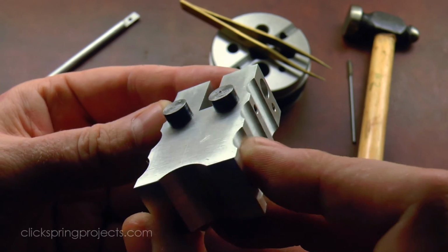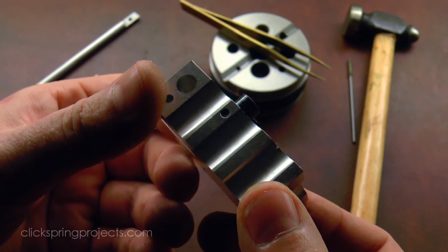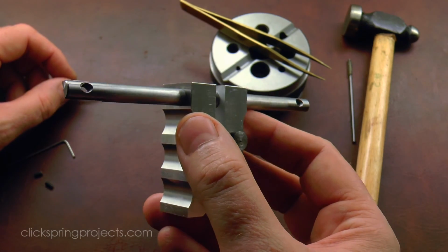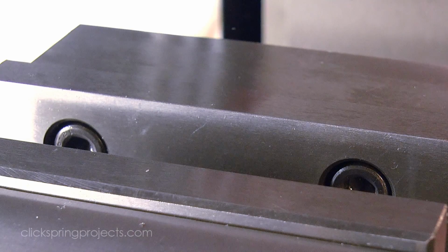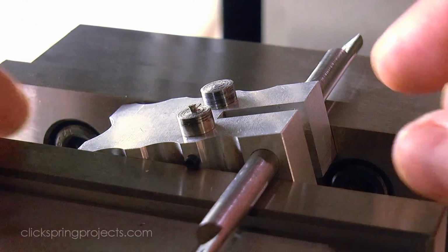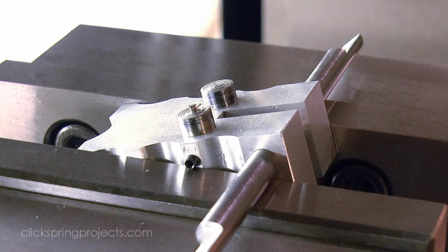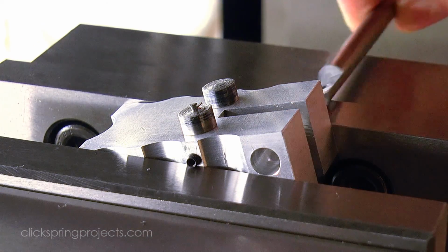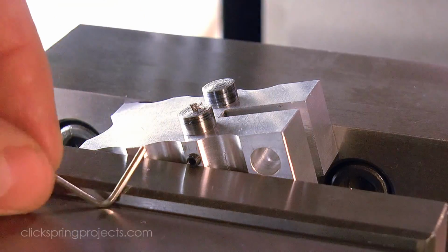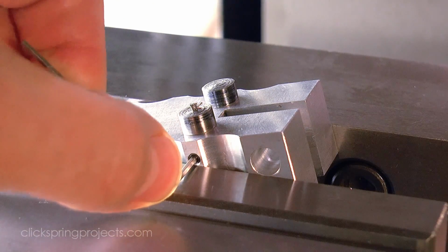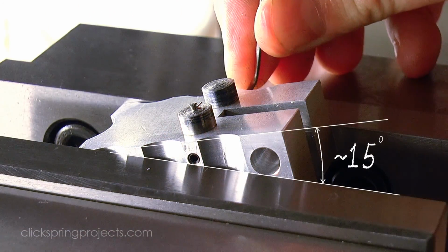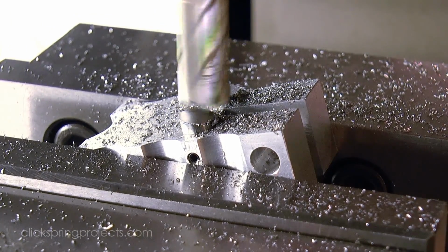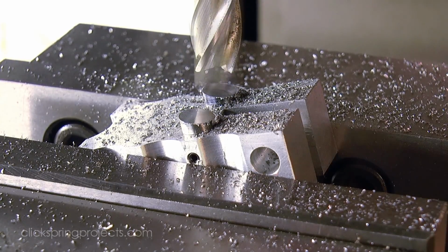Now, as it happens, with all of these holes in close proximity, there's an opportunity to use the various shafts, pins and screws as a crude sine bar to conveniently set the correct angle for the fixture in the mill. Just drop the fixture into place like this and then close the vise. Once the fixture is being held by the vise jaws, the grub screws can be tightened down on the button cutters. Now of course, it's not overly precise, but it doesn't need to be. It makes setting the angle dead easy, and it'll certainly give us an angle close enough to the 15 degrees that we'd like to see.